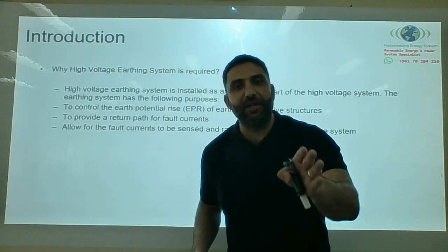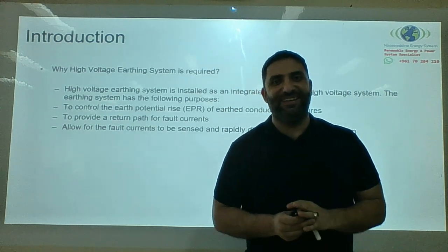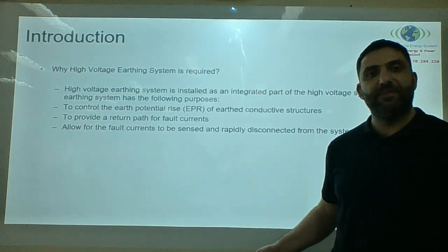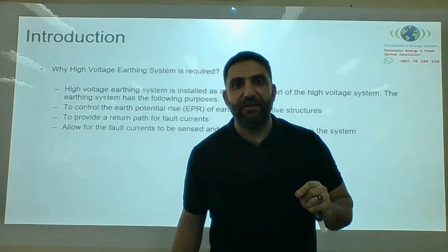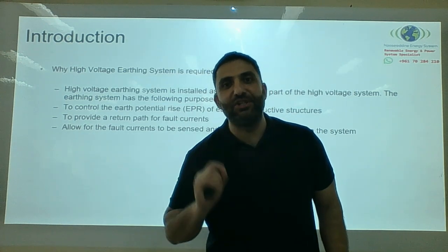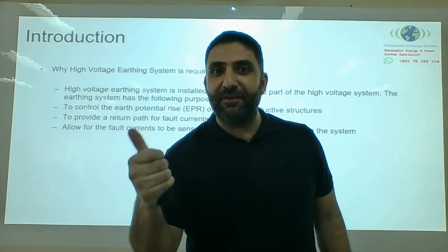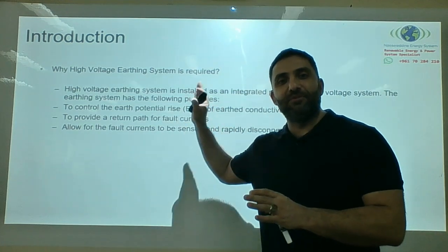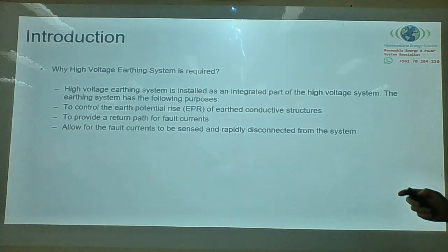For those who work in the design of a circuit breaker or a protection relay, they will understand the importance of this. Depending on your fault magnitude, the relay trip time will change. It's very important to understand primary clearance and secondary clearance time, which we will discuss when it comes to human safety, in another lecture.